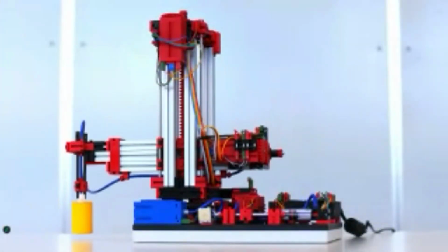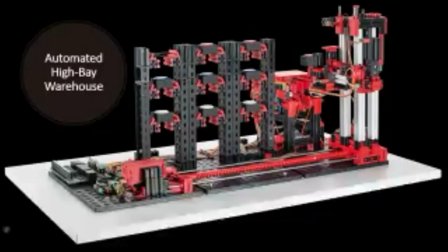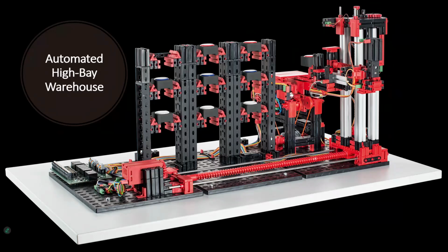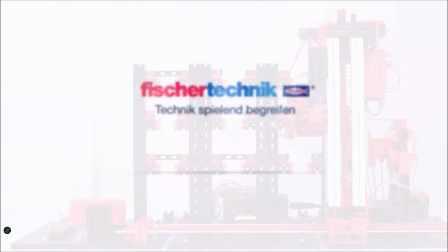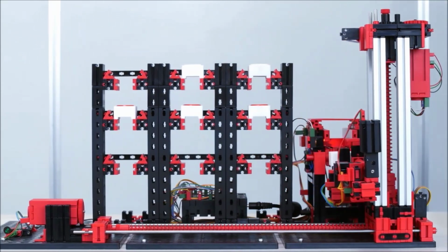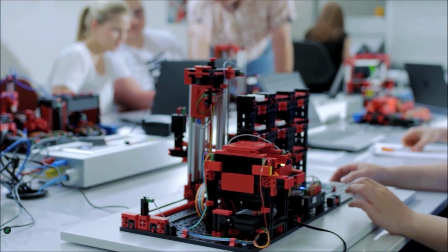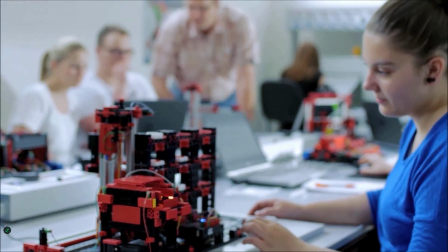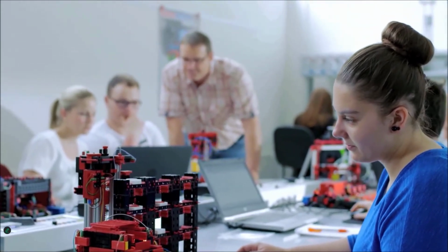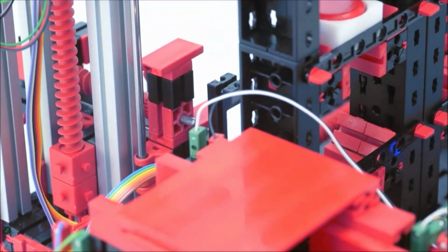The next thing we're going to look at is the high bay warehouse. Now, the model you're going to see here is a high bay warehouse and it features a transfer station with a conveyor belt, along with a shelf stacking mechanism for storing and retrieving workpiece carrier trays and 9 individual storage spots for the trays to be placed. Components on this model include two encoder motors, two mini motors, four push button limit switches, two photo transistors, two LED light barriers, and a selection of different colored workpieces along with carrier trays for each.